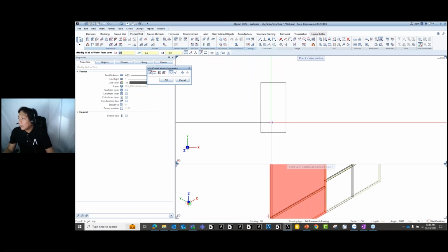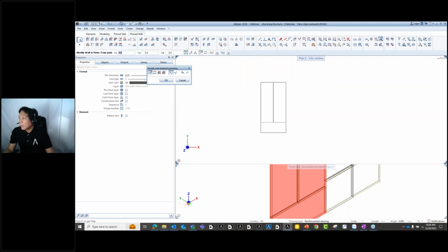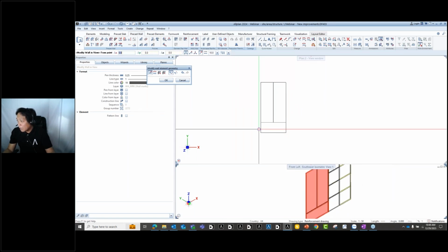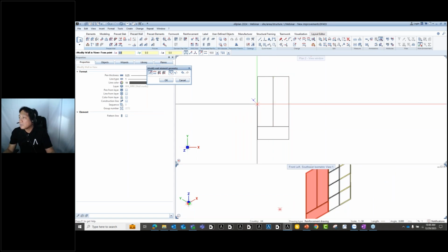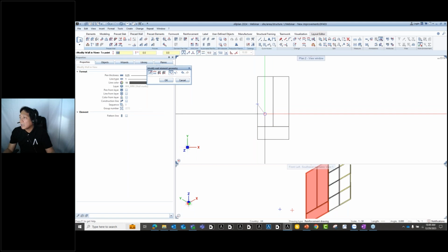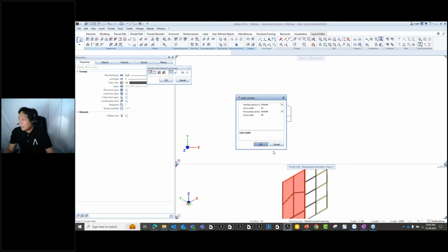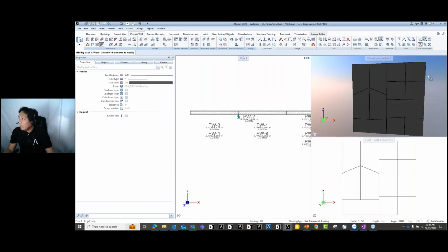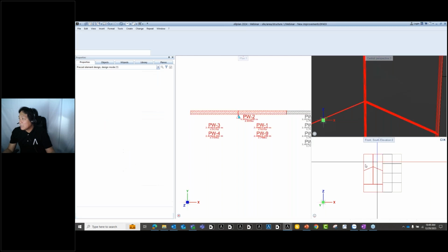And then also from vertical, I can create from here to here, escape. So I will now have my two walls. And of course, this is customized, so you can also have the slope division, incline division. So let's say from here to here to here, make it equal. Then I can say escape, and then I will have my wall now. As you can see from here, I already have divided my walls according to my needs.